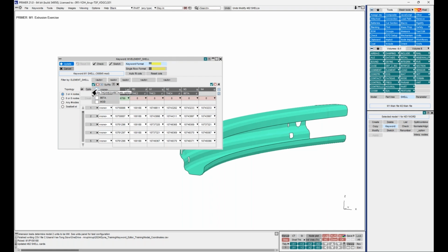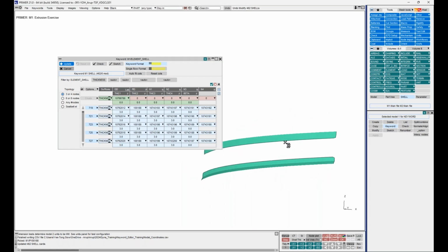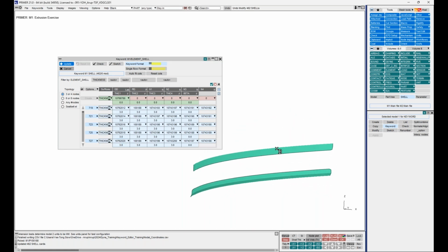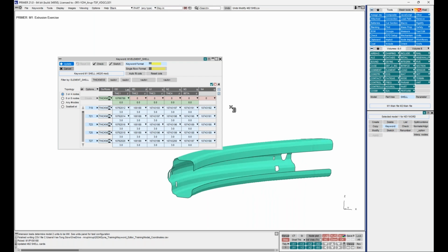If I just untick none, you can see that this instantly shows all of the elements that I've just made changes to. If I press options and then select all, and then right click and only, this gets the right elements that I've just worked on. I'm going to press U on my keyboard again to get everything back up on the view. I'm going to put thickness 1 as the thickness quoted in my parameter. I can do that by using N and then thick.